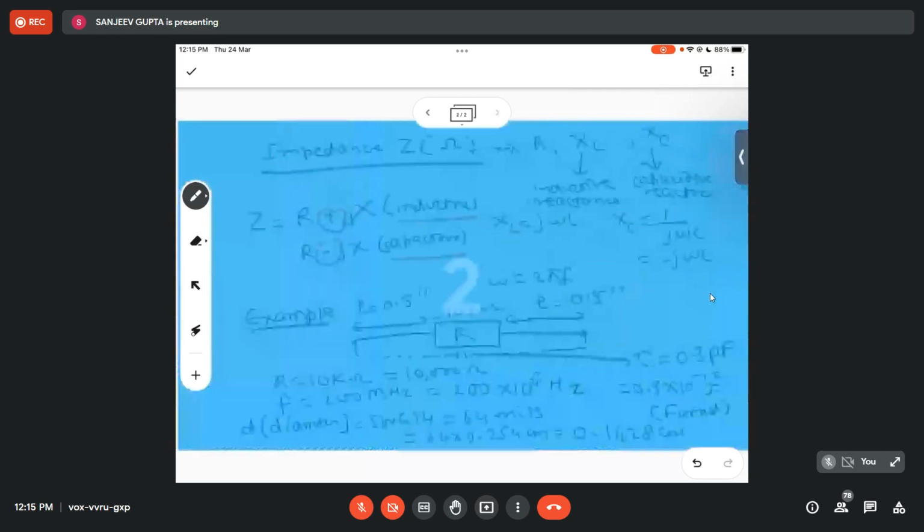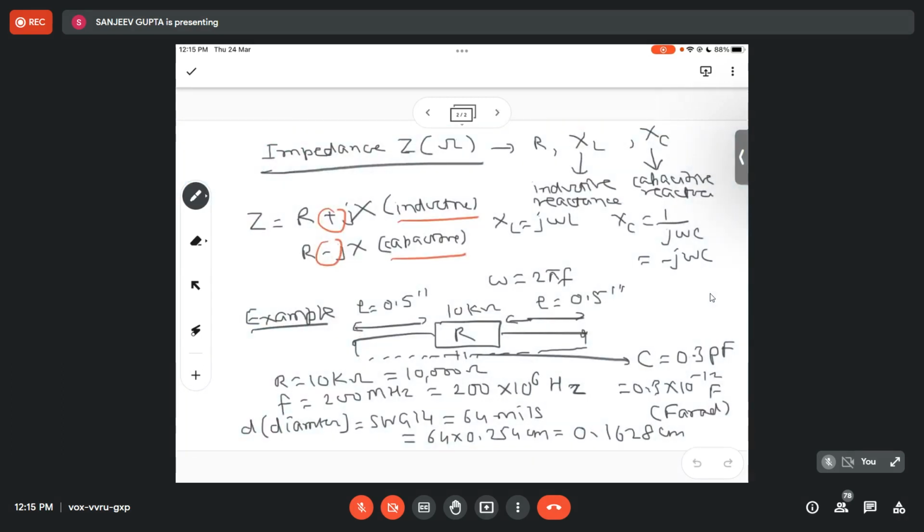So how much trouble do I have to go through now? For a simple resistor which I want to use at 200 megahertz, I have to first compute the length of the wire, then measure the diameter of the wire, then compute the inductance and so on, as we'll discuss, and the capacitance value which is provided by the manufacturer. I'm showing this by the dotted line. This is my wire, and this is a stray capacitance. Okay, now let's see how to work out this thing.